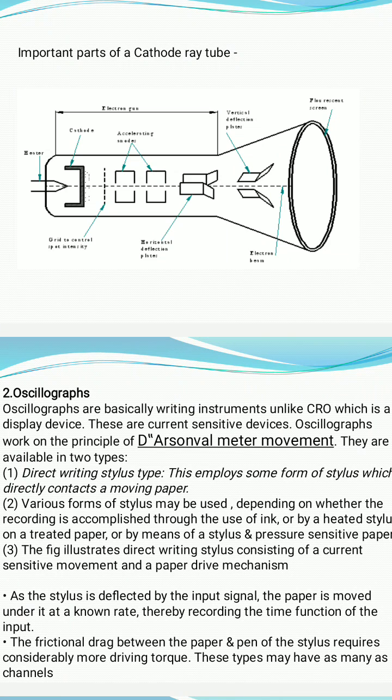The XY plotter has a plate having two beams, one x-axis beam and the other y-axis beam, and these beams have a pen at the bottom side which moves on the paper fixed to the bottom plate. When the output signal from the primary transducer is supplied, the beams move and form the images or graphs with the help of the pen on the paper.